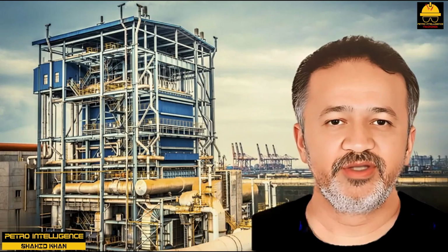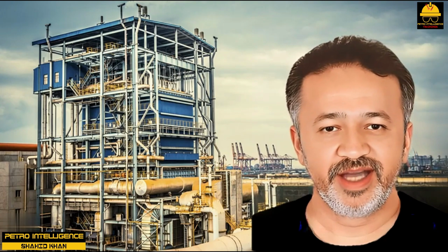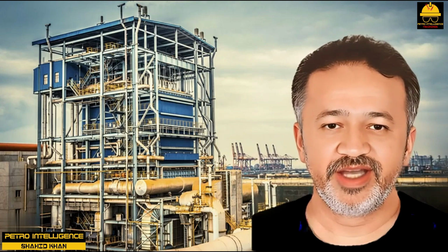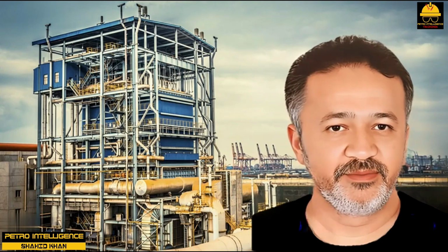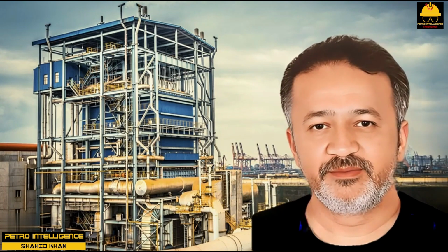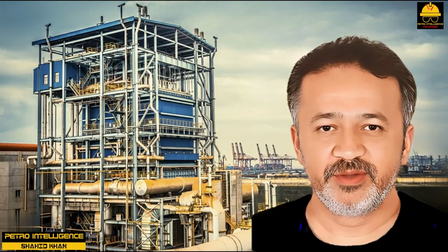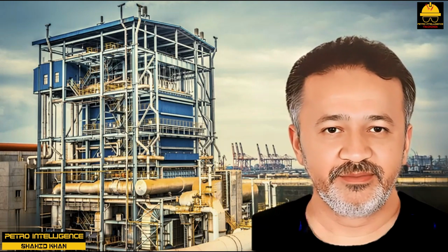Spiral tube insert. The spiral tube insert is a metallic coil stretched over the length of the tube and held in place at each end by straight wires. In operation, when fluid flows through the tube, the spiral coil vibrates axially and radially. The concept is that this vibration reduces fouling and increases flow turbulence, producing an improvement in the heat transfer coefficient.